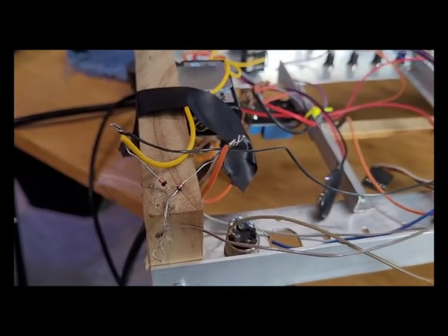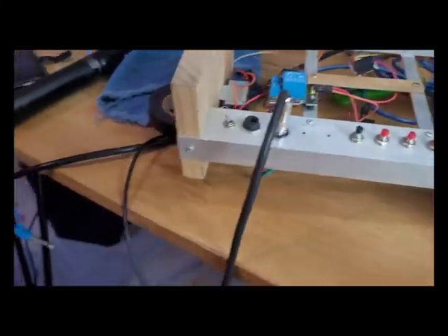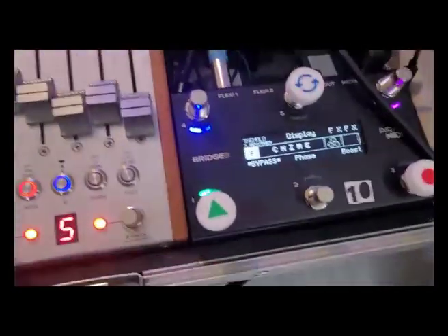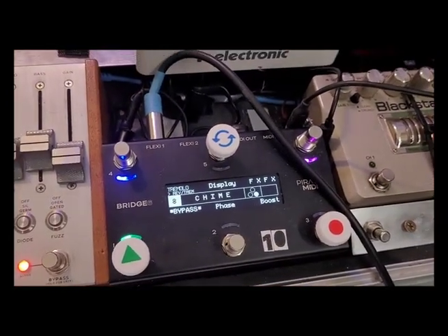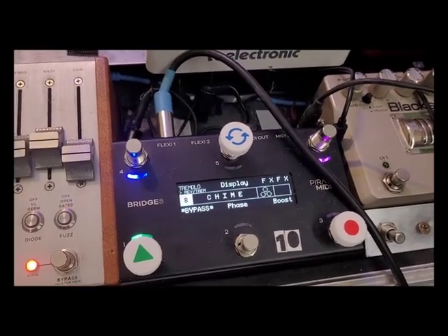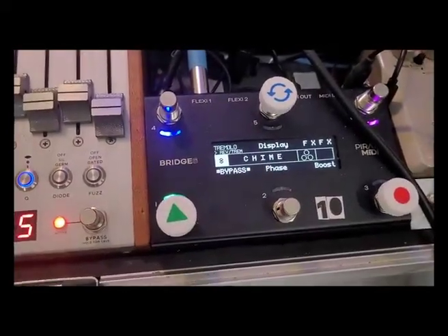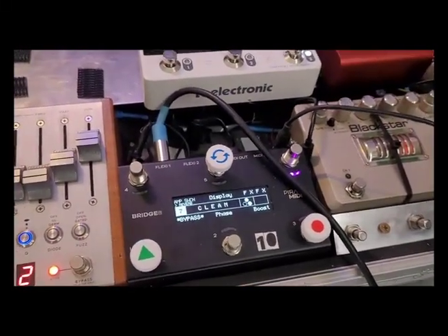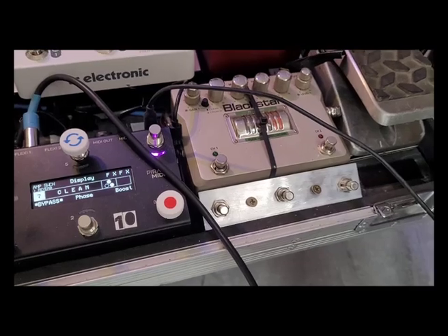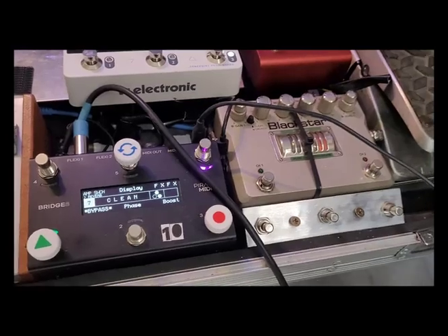So I'll now try and turn this over without sabotaging my efforts. And so I'm going through the switches again, 1, 2, and 3. First switch is doing its thing there. The second switch is tip and ring. That's switching the tuner motor on and off. And the third switch is changing the patches. So it works. You can use one TRS cable to do 3 auxiliary switches, but unless there's some other way, you've got to use those diodes to make it happen.